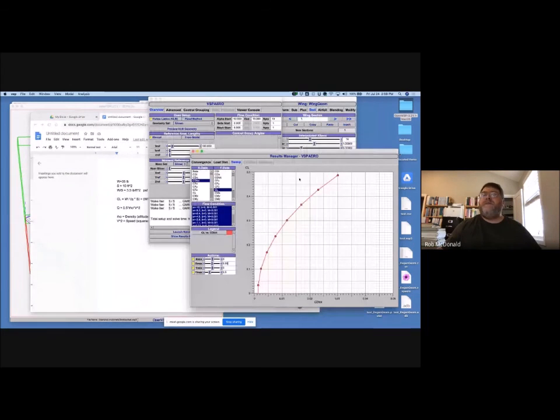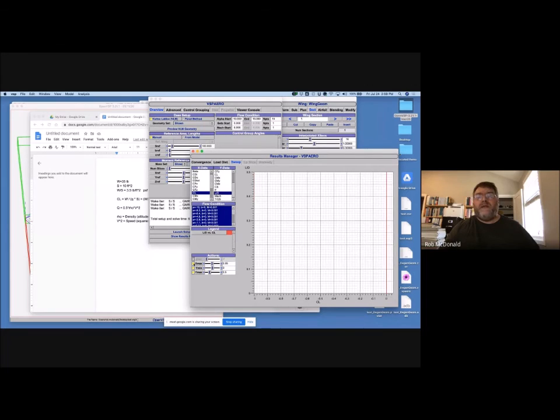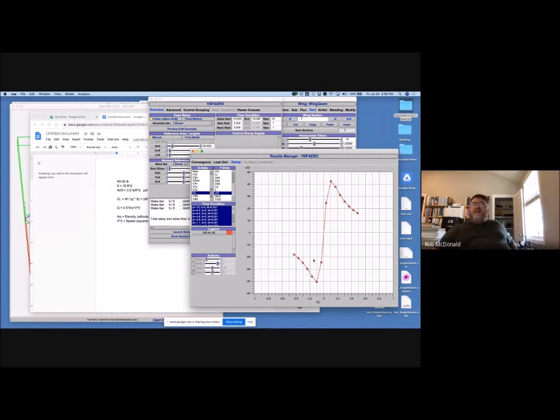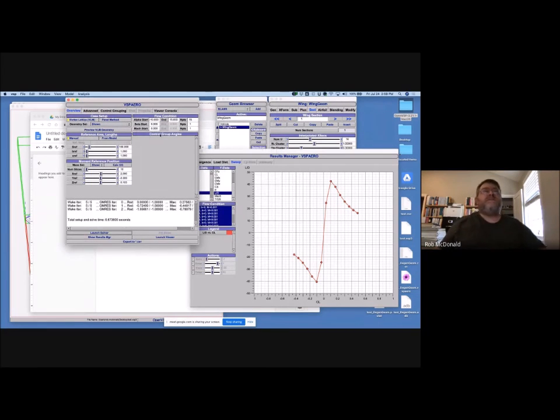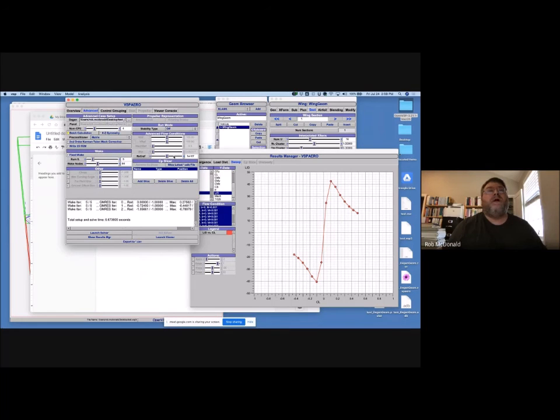So if we look instead on this chart and we look at the X as CL and the Y as L over D, and we let it figure out the axis limits, this is pretty typical of what you're going to see, and this is ugly. Part of the problem right now is that this analysis that we did does not have a believable amount of parasite drag. And the Reynolds number, the CF equation that we've got right now, this airplane wouldn't be up at 1 million Reynolds number. I mean, that's at 10 million even.